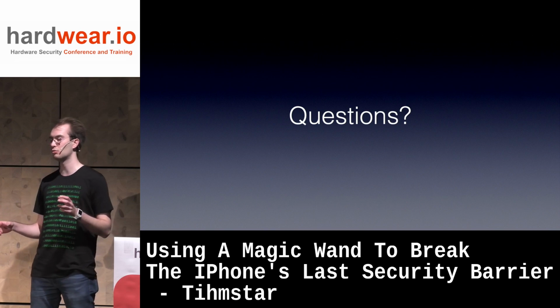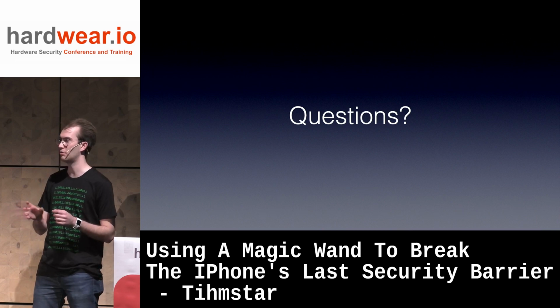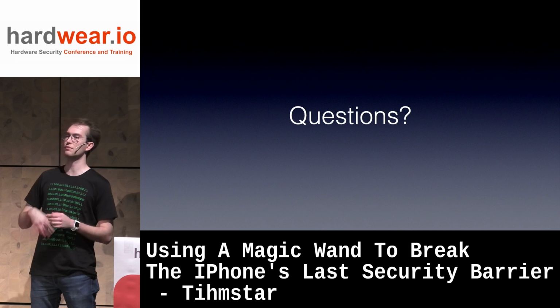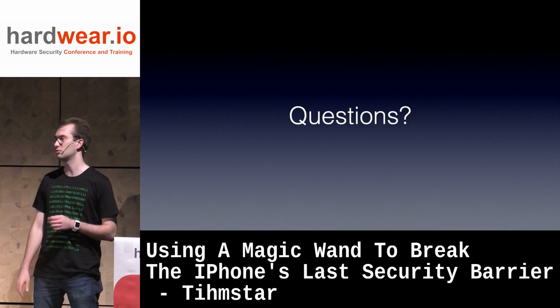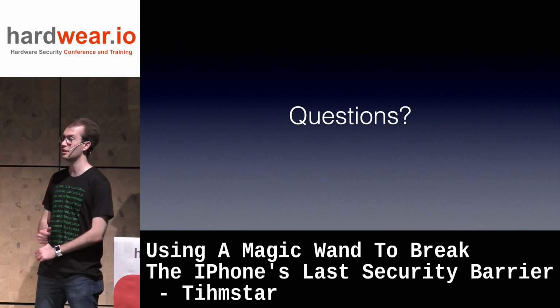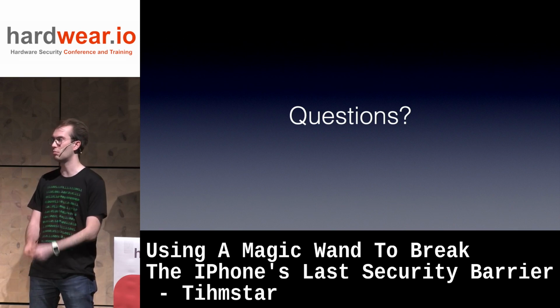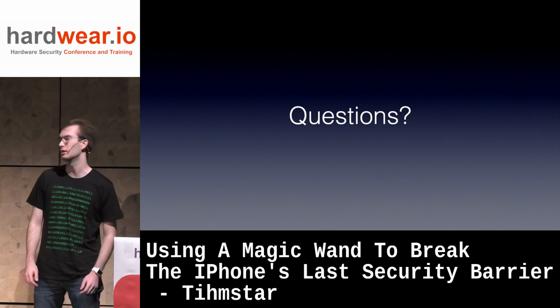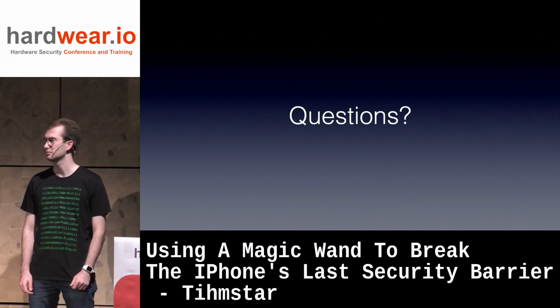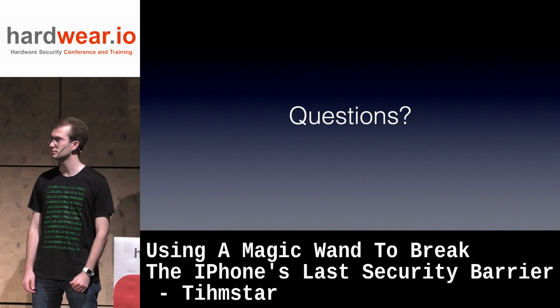So you had to run the attack on unaligned traces, which again are very jittery. And because of that, you needed to use roughly the same amount of traces. So it's possible with both EM and power traces, but due to the alignment problem, the power isn't better than the EM.